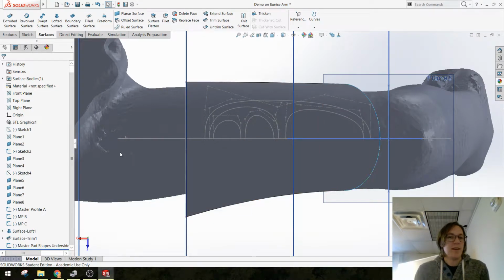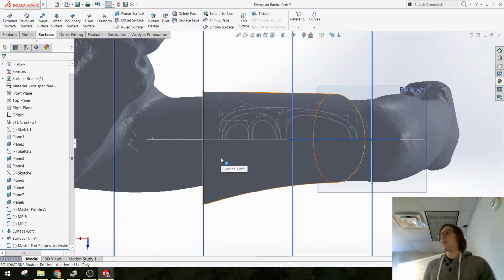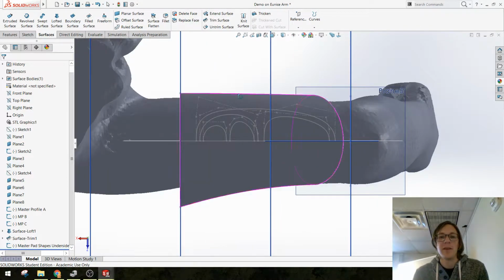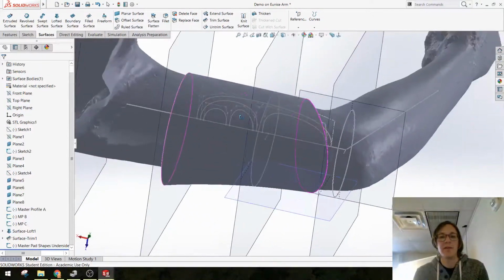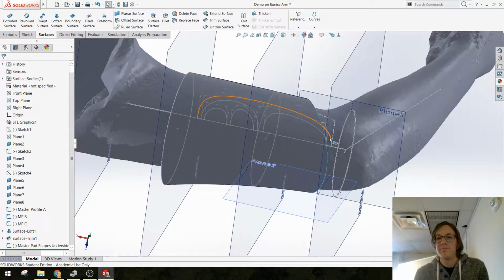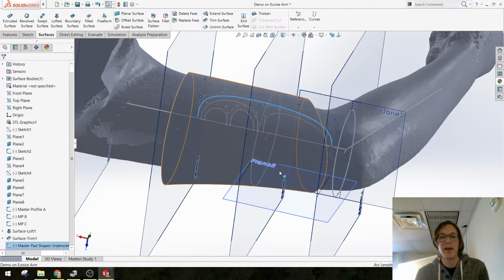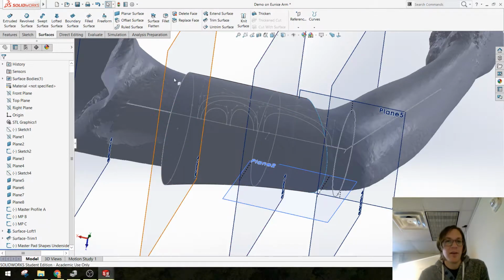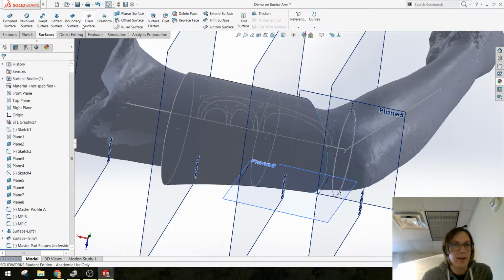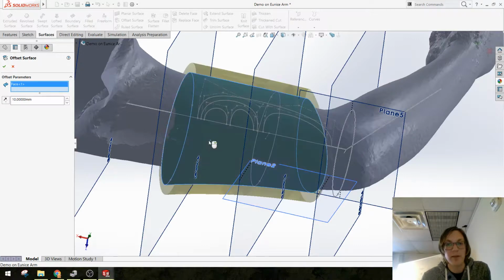Okay. Now, because it's a master sketch, remember I'm going to convert the entities that I want to use out of this master sketch. And because I'm working with a base surface, this outer line, I'm thinking, is going to be an offset of that surface that might be a padded area. I'm going to start by using an offset surface of my main surface.